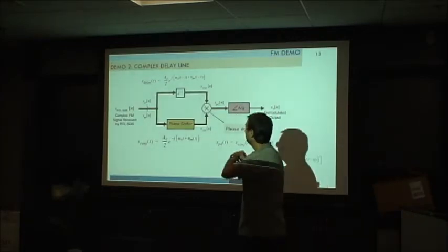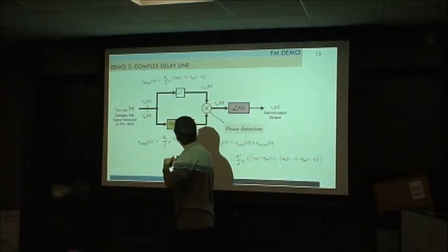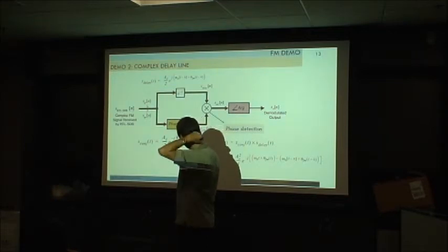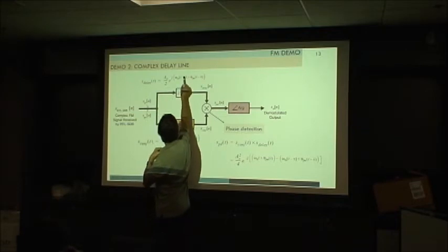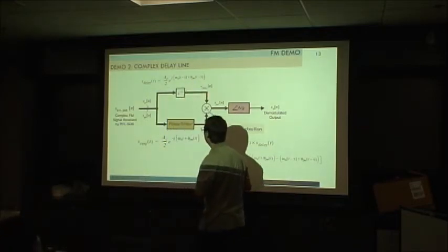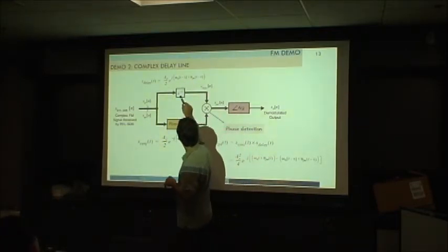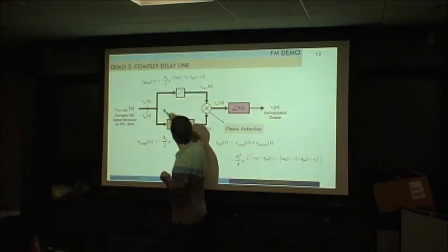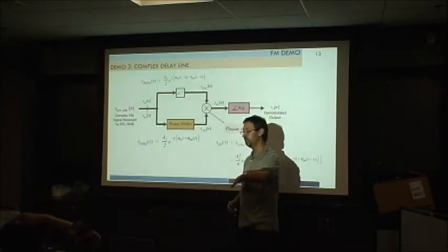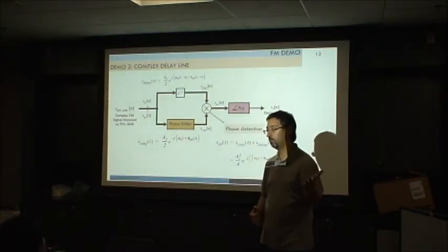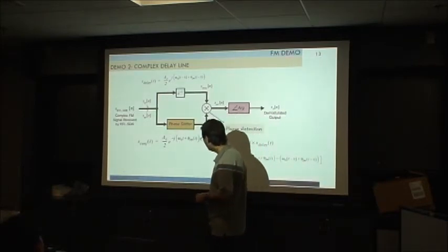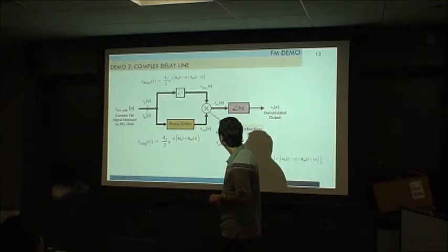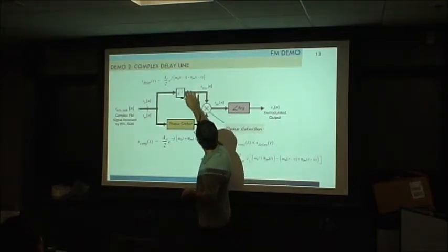Okay. So remember that on the complex representation, what we received after down conversion was something like this without this delay, of course. But what's going to happen if we just make a simple delay here? And on the same signal, if we have a phase shifter of 180 degrees, that is just the complex conjugate. It's really simple to do. Okay? So we take the complex conjugate of that one. So this will be the result and that will be the result.